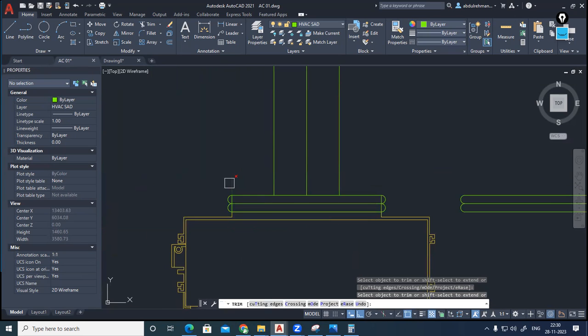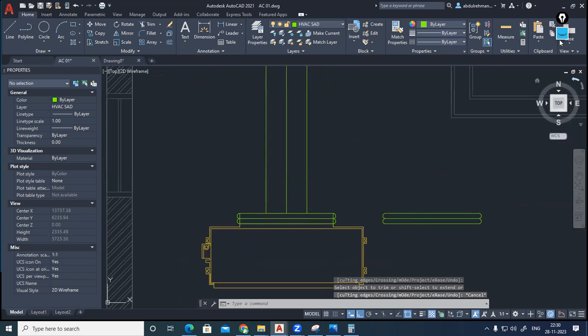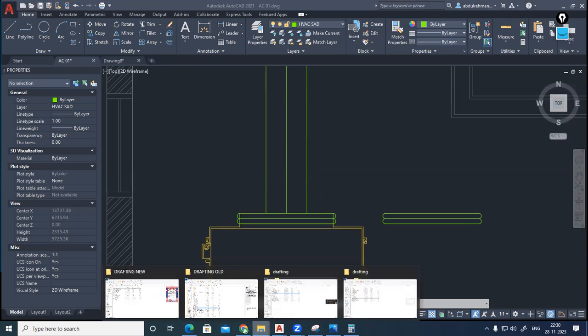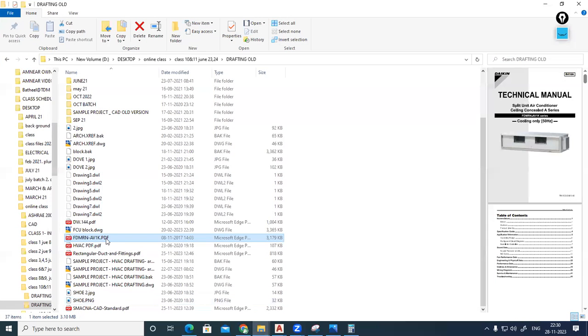Now I should make the machine taper. It is clear that the duct width is 400. The machine is 900 something. So anyhow, from 900 to 400, I need a taper section. The taper angle maximum is 45 degrees. Okay, so you can go to DW 144 standard. I'll be selecting ductwork 144 standard.